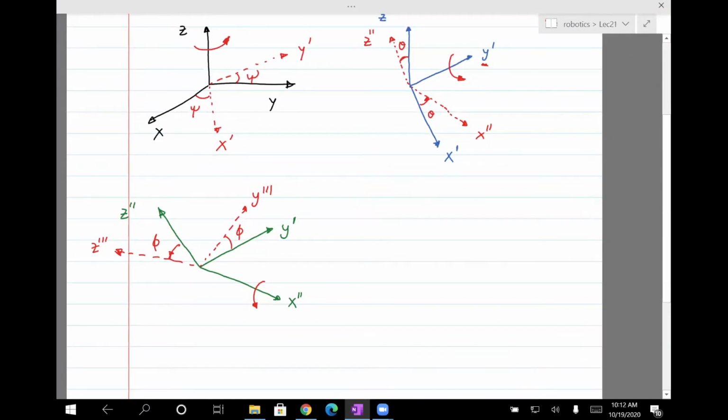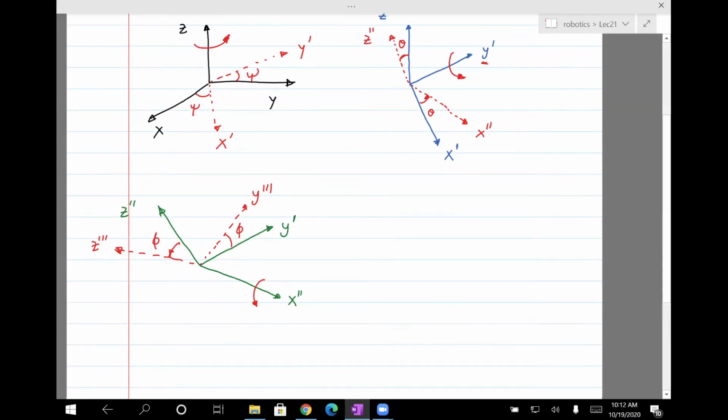If you take an object and you want to visualize this, just do it by say 90 degrees. It's much easier to visualize, but that's what's going on. The axes keep changing, and as I've shown you in the past, these axes are local axes. They rotate as the body rotates. The z-axis will always be pointing along the direction in which I started. But in the global, fixed frame, like I've shown it here, those will change to prime, double prime, and triple prime. Okay, so we have these three rotations.